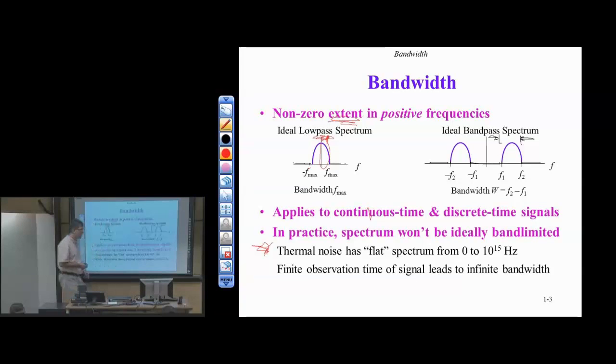Our sampling rates now, tens of gigahertz is kind of where we're at in off-the-shelf test and measurement equipment. It's hard. So that's 10 to the 10, maybe 10 to the 11 if you really got some really good stuff. 10 to the 15th is way beyond what we would sample. So for the frequencies we care about, we're going to have thermal noise. And I forgot what happens beyond 10 to the 15th. I remember having this in class as an undergraduate student. I remember it falls off, but I don't remember how.